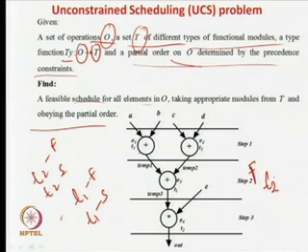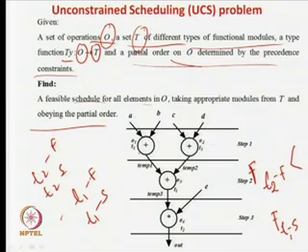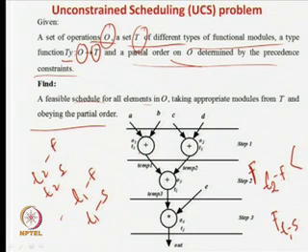It even happens that the frequency of T2 faster, that is the frequency of the fast multiplier, will also be less than the frequency of T1 slow. That is a very typical thing you have to understand. Again, I have to re-emphasize, multipliers are very complex circuits compared to adders. So, even if you take a very slow adder, in this case say T1S, the frequency of T1S, that is the frequency of the slow adder, will still be higher than the frequency of the fast multiplier. That is a very interesting thing to observe: even if you take a very fast multiplier, the operating speed of your slow adder will still be higher than that.